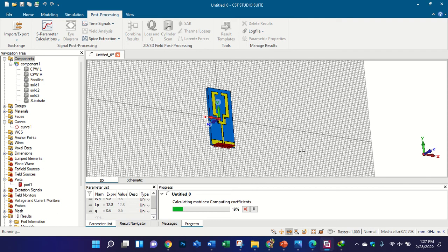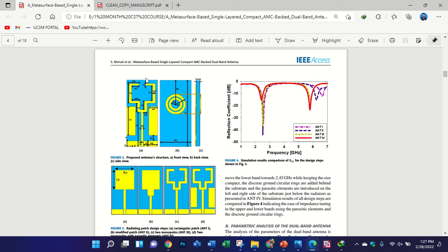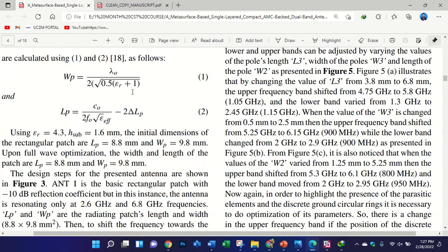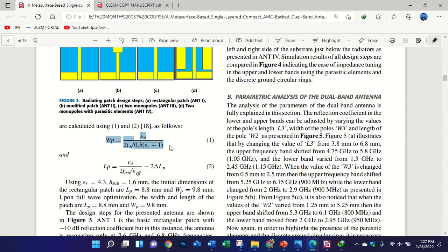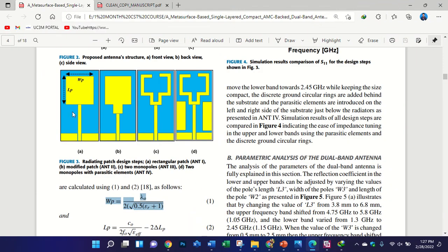Sir. Yes. So for a paper publication, do we require some kind of mathematical justification for the design or not? Yes, just for the optimization. You can see while designing this antenna I did not follow any mathematical equation, but in the paper I added these equations. The optimization result may be different for different dimensions; these equations are just for the starting point, because your design starts from the patch antenna, then you modify the shape.